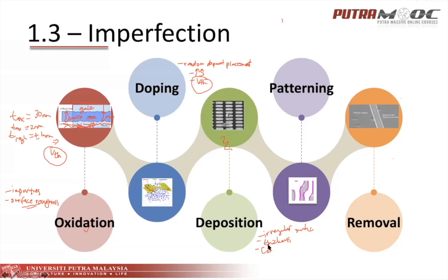Okay, thanks. So COX could also be affected by imperfection of the deposition process when we have metal layer formation. This can occur if you deposit an oxide layer and you have surface roughness or irregular surface, or different thickness of the deposited material, and that can vary the COX parameter.